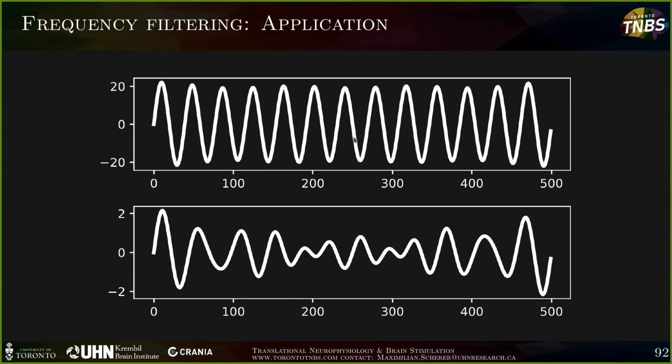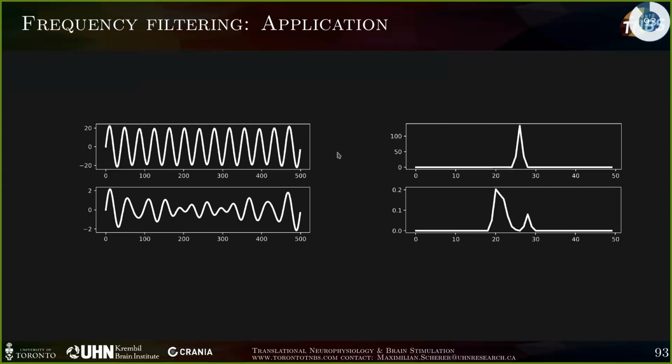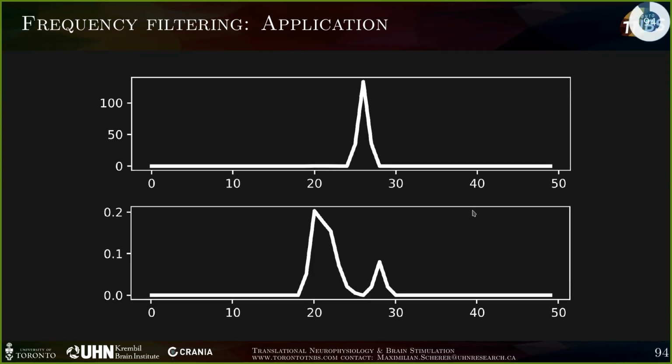With the upper one, we appear to have a significant contribution at a certain frequency that totally dominates our signal, making it almost impossible to see anything in there. If we transform that via FFT into a power spectral density, we can see that the upper signal has this super high peak right at 27 Hertz, whereas the signal that we actually wanted looks like that.